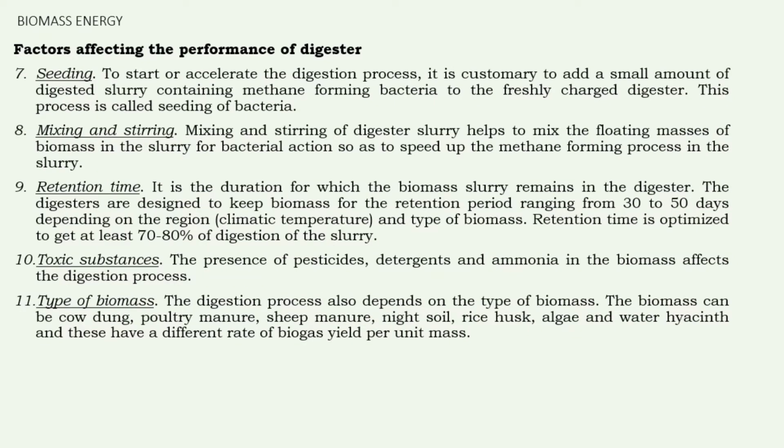Next one is seeding. To start or accelerate the digestion process, it is customary to add a small amount of digested slurry containing methane forming bacteria to the freshly charged digester. This process is called seeding of bacteria.